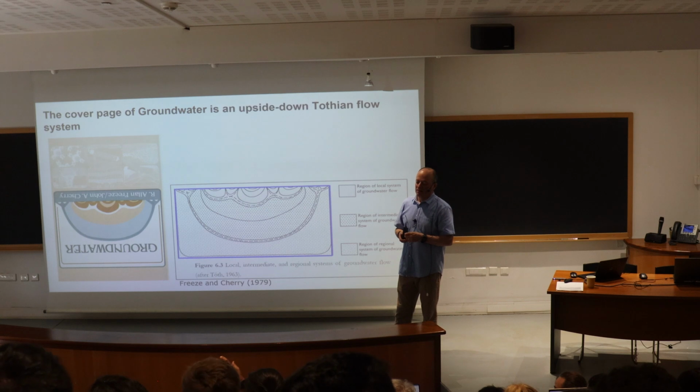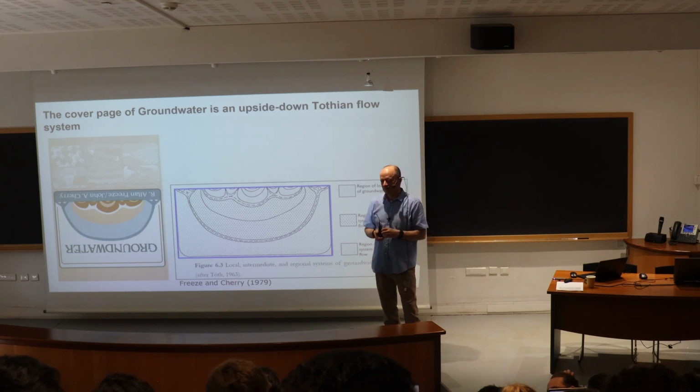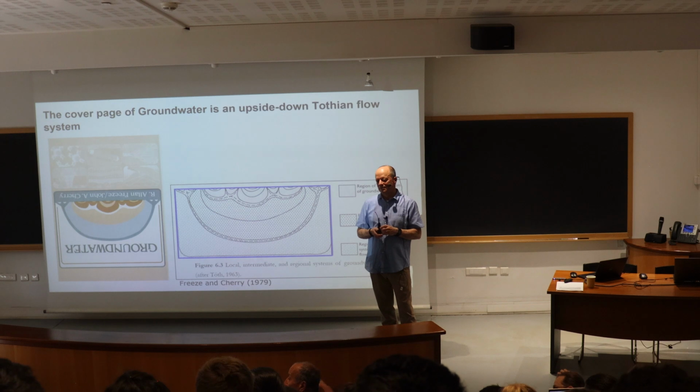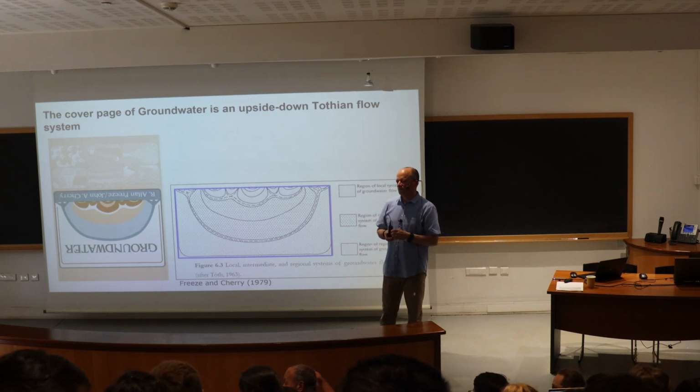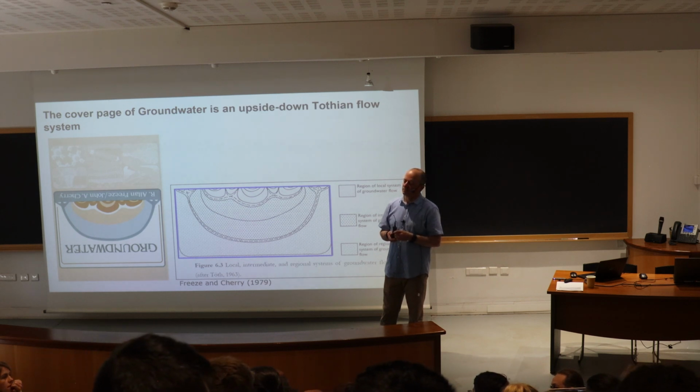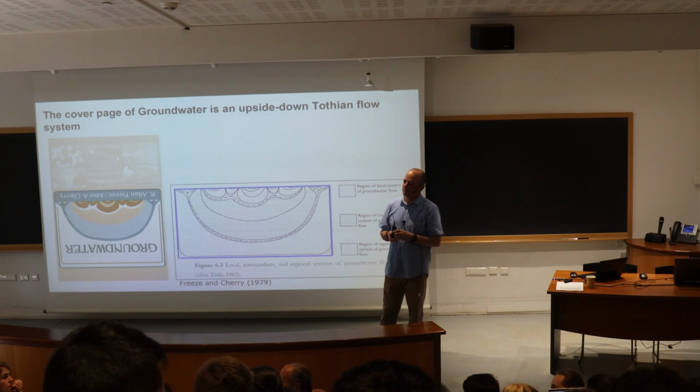So while the REV for porosity can be a few cubic centimeters, you can increase the sample, you're not going to get different porosity. When you increase the sample of fractured rock, this is based on modeling and some measurements, the REV for discrete fractures can be in the order of many cubic meters of rock samples. We're talking about more than 10, 20, 30 cubic meters in which you can start to characterize the behavior of that formation in terms of discrete fractures.